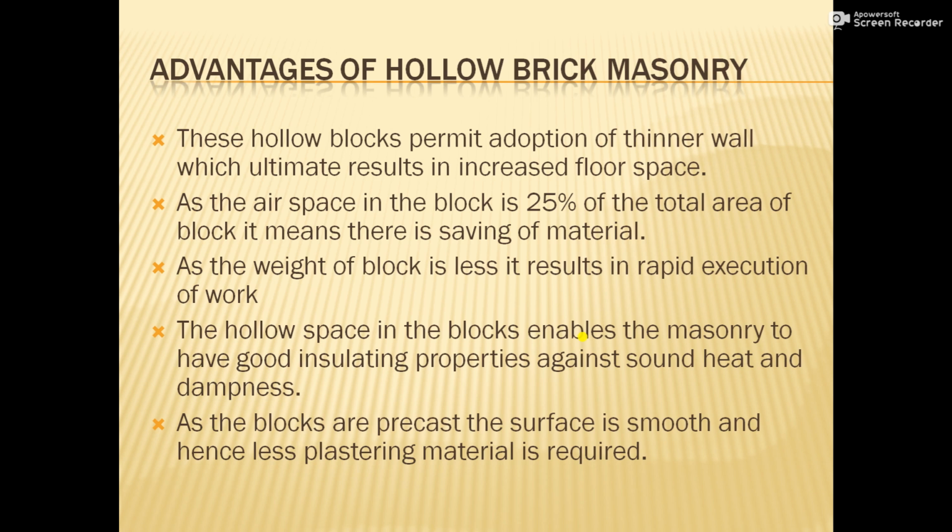Second, as the air space in the block is 25% of the total area of the block, it means there is a saving of material. As we provide a core in the block, because of that core we are saving our construction material. Third, as the weight of the block is less, it results in the rapid execution of the work. Whenever the masonry work is going on, as the weight of the block is less, because of this light weight, rapid execution of the work is possible.